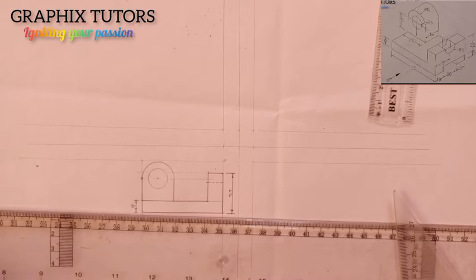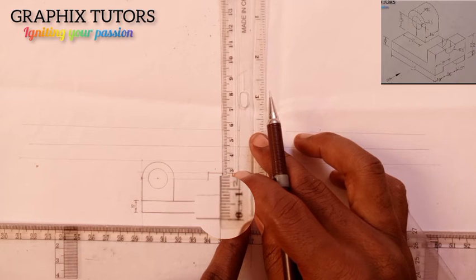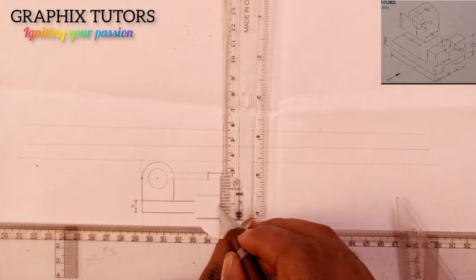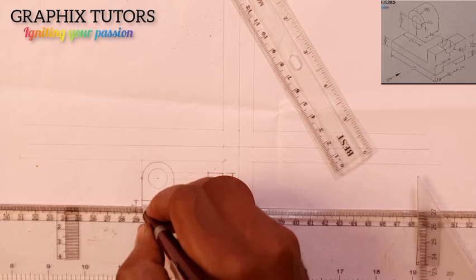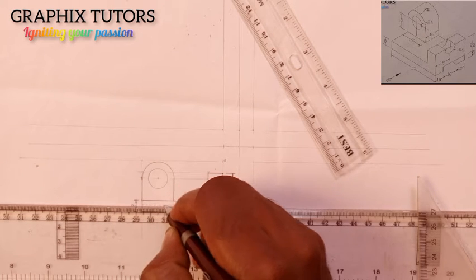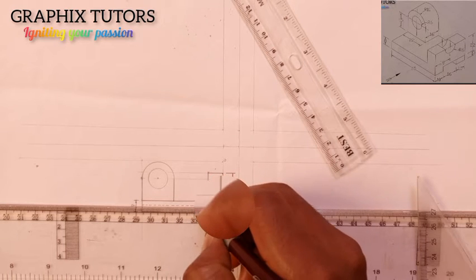So from here, I'll measure 5 in. This is a 5 here, and I'll use my hidden line to show that there's a cut through in. Thus, evenly spaced lines. They call them hidden lines to show hidden features.